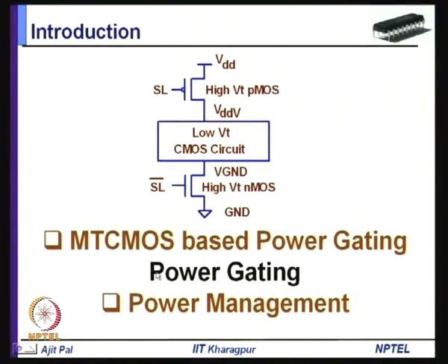That is your management, and in fact, power gating is precisely done in this way. That means you are essentially doing power management by gating the supply voltage, and that is the reason why it is also called power management. So, the same thing is being done whenever you do MT CMOS based power gating or power management. Any of the three actually means the same thing.